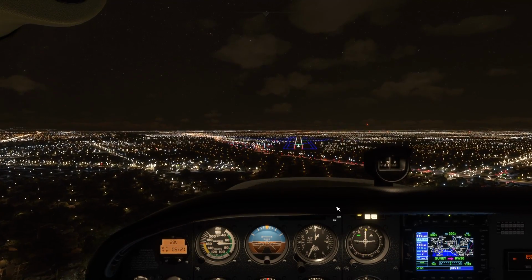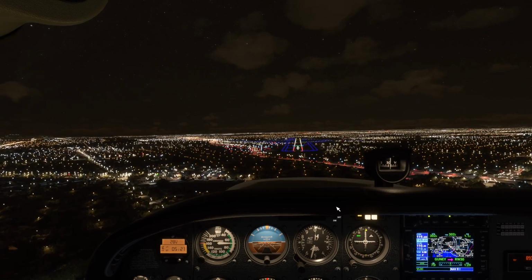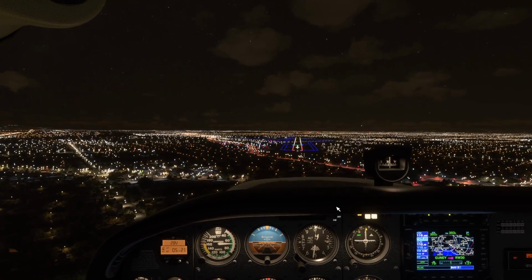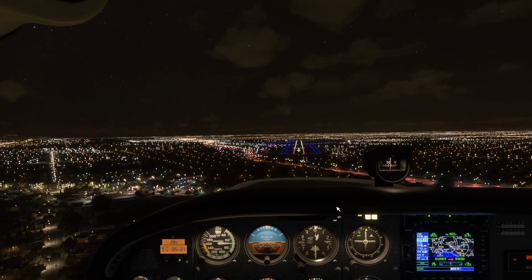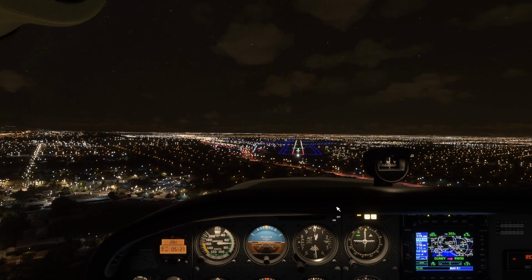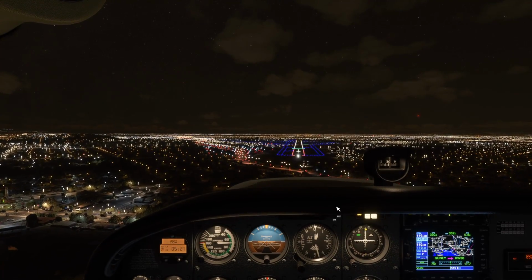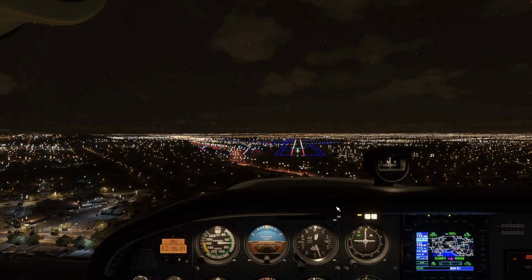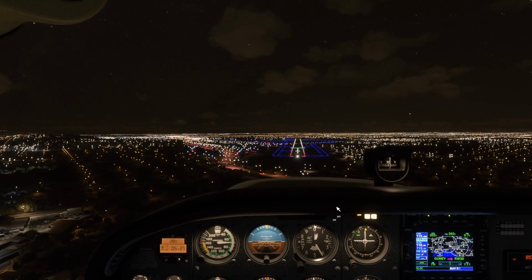Now we won't stall unless we're under 40 in this aircraft, but our landing speed should be around 60 to 70. And it's up to you when you disable autopilot. You can wait until it gets almost all the way down and touching the ground before you just flare the nose up a little bit when you're cutting the power to idle. And that's just a procedure you do in the Cessna 172.